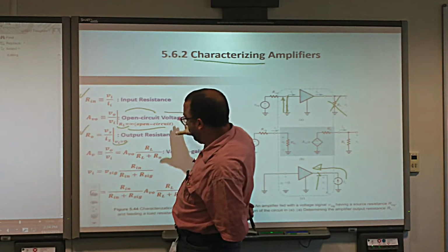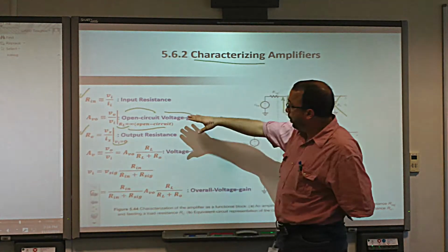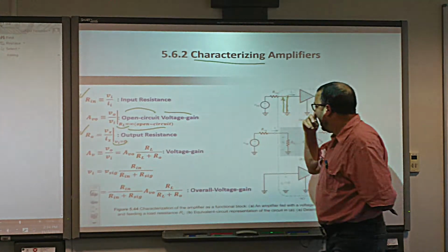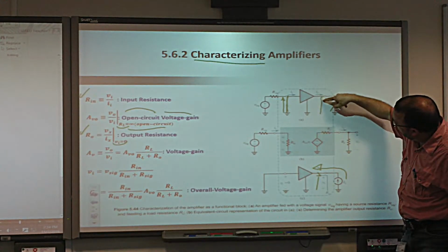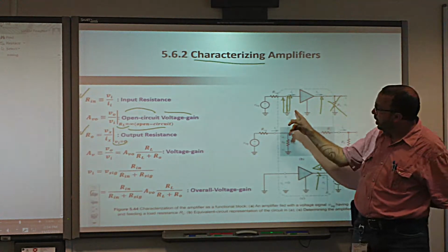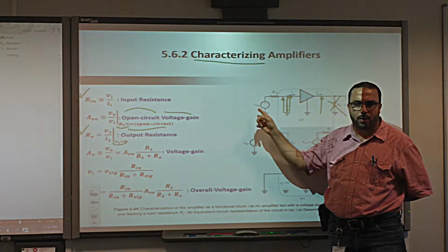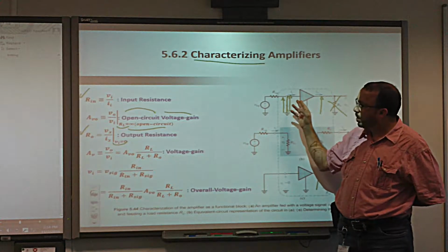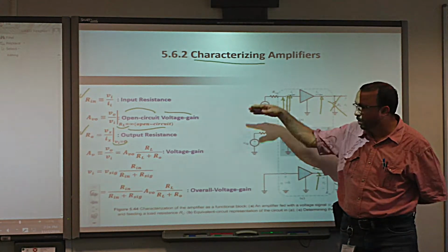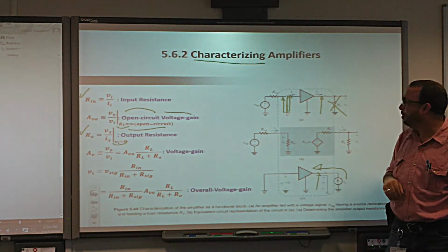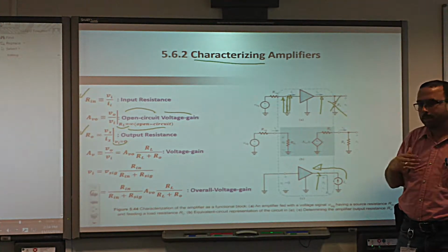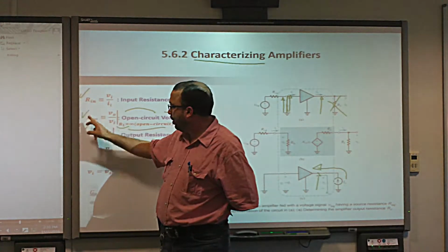So, what is that? I'm here. Good. And for that, I know the voltage gain is the output voltage divided by the input voltage. Boom. But the output voltage at the output of the amplifier and the input voltage at the input of the amplifier. Because this voltage is different from the signal or the source voltage. It's different. When we say the input voltage, it means right at the terminal of the amplifier. Not before. Right at that terminal, the input terminal. And when we say at the output, right at the output terminal. Good? Bingo.